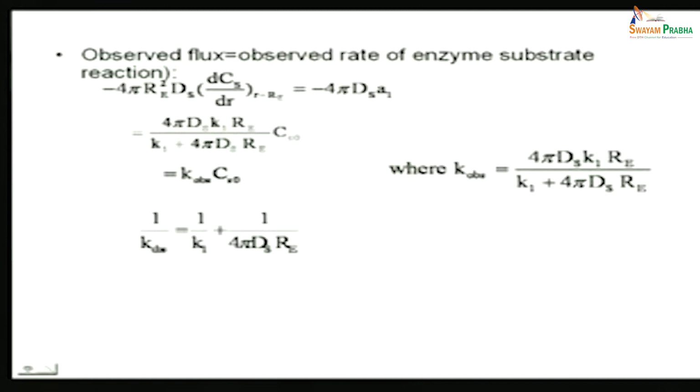So, this is one of the cases. I am not sure if you have done such an example before, where you have done examples where 2 mass transfer resistances or 2 heat transfer resistances are in series, but I am not sure if you have done a case where 1 heat transfer resistance or 1 mass transfer resistance is coupled with a reactive resistance. If you have, then it is an interesting thing. Otherwise, this is one of the examples of resistances in series, but the only difference is that the 2 or 3 resistances we are considering are not necessarily of the same type. So, you have a reactive resistance out here and a mass transfer resistance, and you are adding them up to get your total resistance.